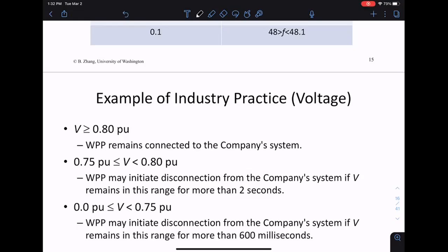But you are sensitive to voltage. There's not much you can do about the grid voltage, which will create different power flows in your circuit. Whereas for frequency, you essentially have an isolation stage because of the power electronics. Voltage, you're more sensitive to.